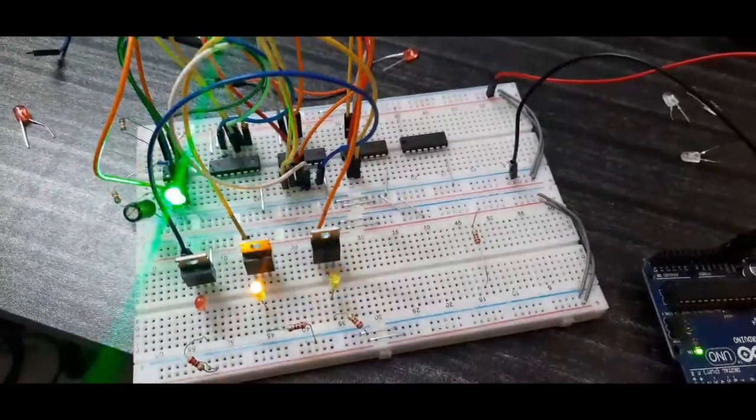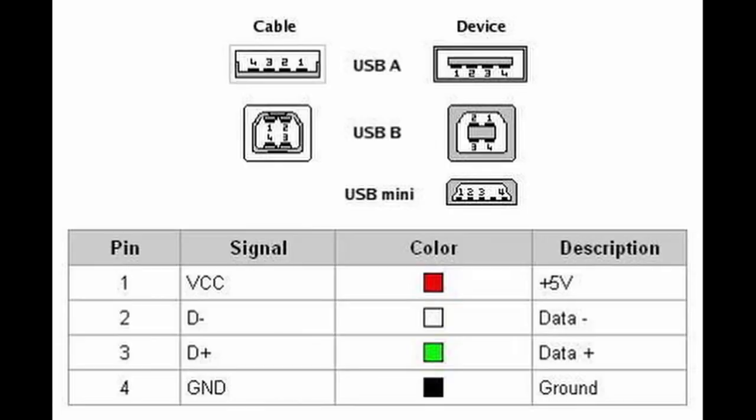To supply power to our logic circuit and LEDs, we have used a computer's USB port. Modern USB ports have the capability of sourcing 5 volt and 500 milliampere max, so it is adequate for our project with enough headroom. A USB-A cable was stripped to find the red and black marked wires that source 5 volt and ground respectively. An SPDT switch with 250 volt handling capability was used for the ease of turning power on and off.